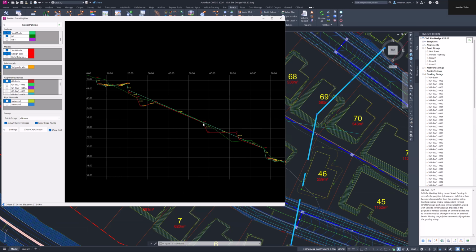So one thing that I don't want users to think is that there's maybe an issue here. The difference between a surface and a model is that the model is picking up the line work, or basically the breaks on the line work, of your model, the codes, centreline, batter, boundary, footpath. The surface option is picking up the triangulation of that surface. So wherever there's a grade break along that surface, this is probably not the best example. Probably find another one up here.